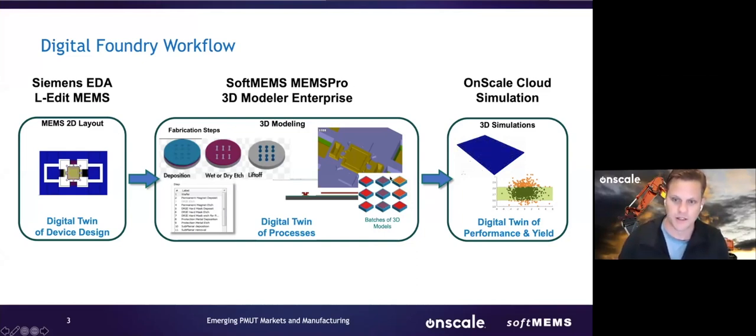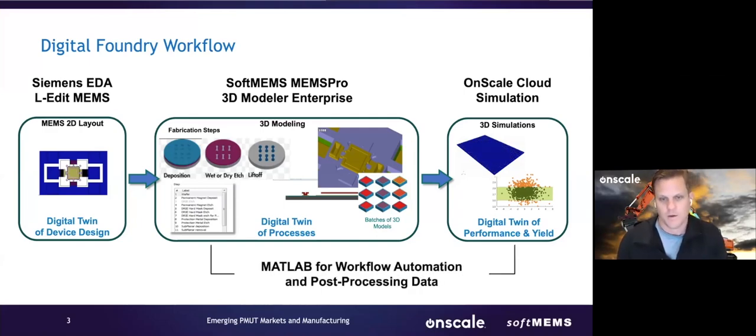You can either simulate individual cells, or you can simulate an array, like what we're showing here, where there's a beam forming pattern moving across this array. And if you follow this digital prototyping and digital qualification workflow, ultimately you can understand how your device will yield, or you can go back and tweak the design to make it more robust and improve potential yields when you move on to actual fabrication stages of the R&D process.